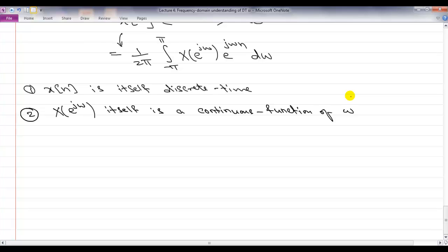Okay? If a signal is aperiodic, if it's not periodic, you can't have just one or two frequencies, because those frequencies likely will have a periodic sinusoid associated with it. You can't reconstruct that original signal. So you often need an infinite number of frequencies.